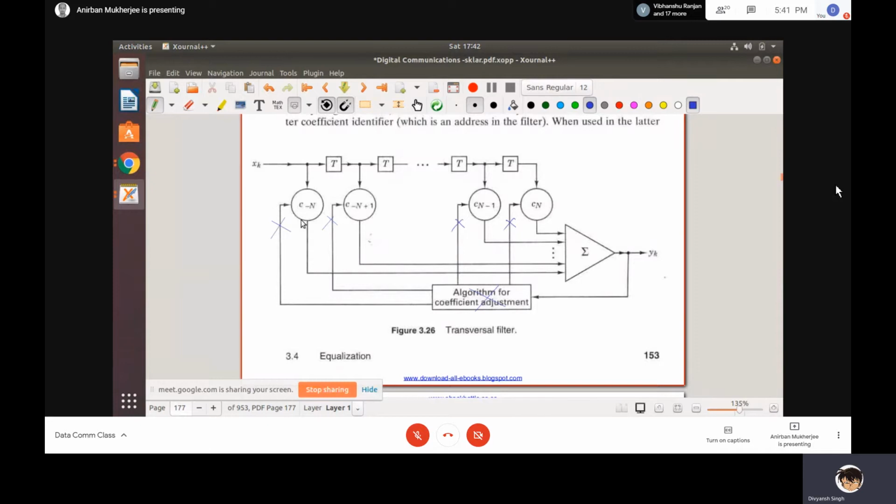So you are just summing c_k x(t minus k minus n) kind of thing. That is a delayed input and multiplication with individual coefficients, added up. This is called the transversal characteristics of a transversal filter. Now the question is, next you come to this